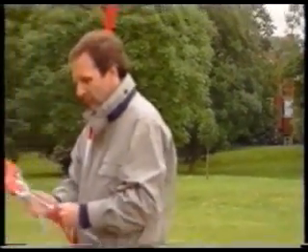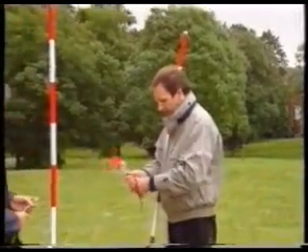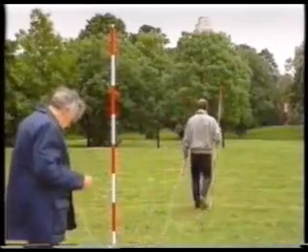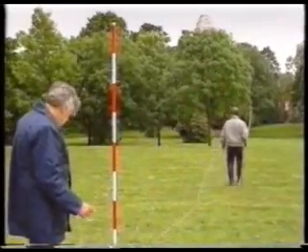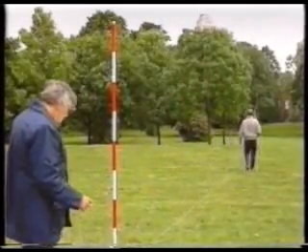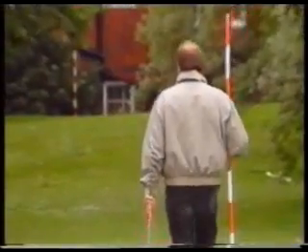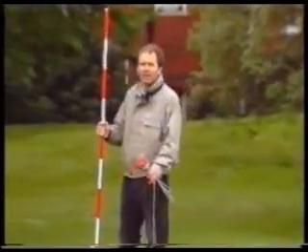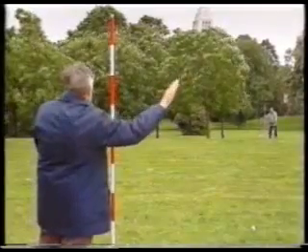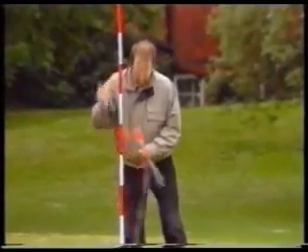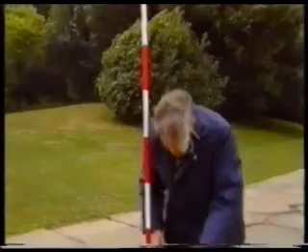The procedure for measuring a long distance with a tape or chain uses a technique known as ranging. Ranging rods have been set up at A and B at either end of the line to be measured. One of the surveyors, known as the leader, sets off for point B carrying a known number of metal chain arrows or marking arrows. The follower does not have any. Stopping just short of a tape length, the leader holds the ranging rod vertically, and the follower lines it up with the ranging rod at B.